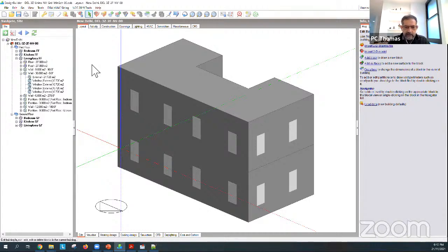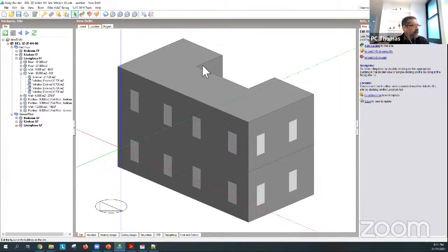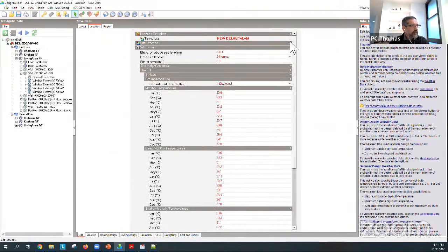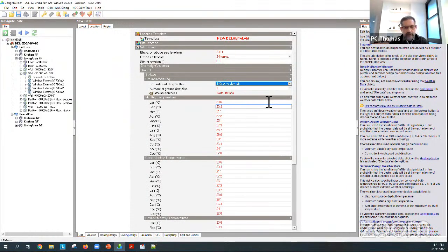What we are doing in simulation is we're doing a calculation every hour. But the ground temperature is a much slower process. You need a different calculation algorithm for it. And a couple of people have built algorithms for it. Okay, there are 2 or 3 ways of doing it. In EnergyPlus, you should read what are the different options for doing ground modeling calculations and pick either standard or pick ground domain. These 2 we know work.